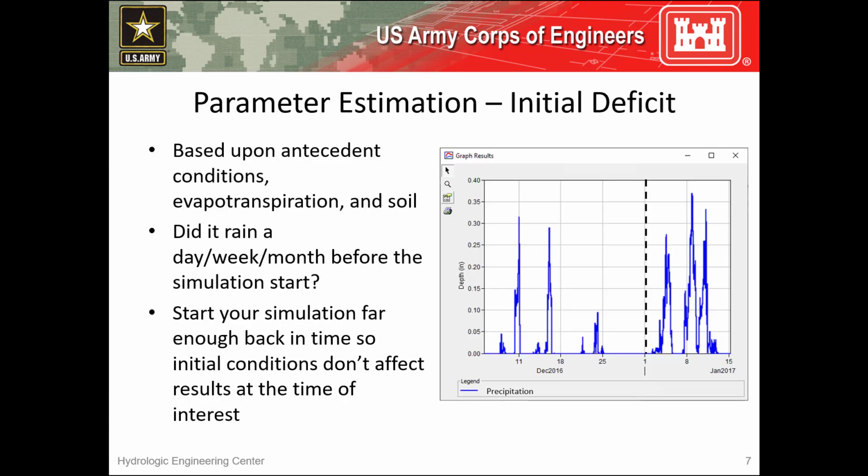Now let's talk about parameter estimation for this method. When estimating an appropriate initial deficit, you should scrutinize the prevailing antecedent conditions prior to the start of the simulation.